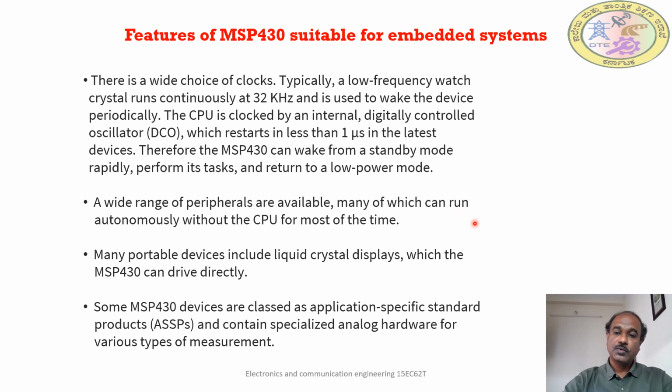In that case, if my embedded system has a liquid crystal display, then the 8051 cannot directly drive it. So when I am using the 8051, I need a liquid crystal display driver, which is required extra. But if I use the MSP430, some microcontrollers of this series are capable of driving liquid crystal displays. So there is no need for an extra liquid crystal display driver, LCD driver. It is not required.